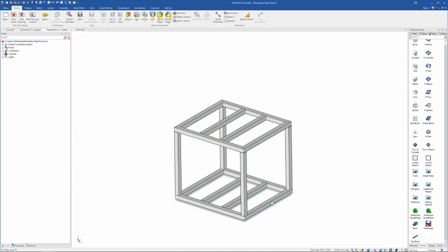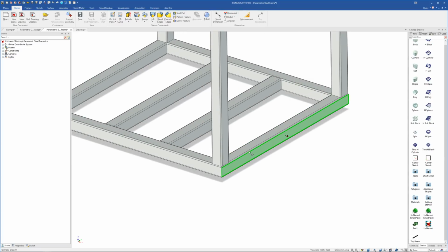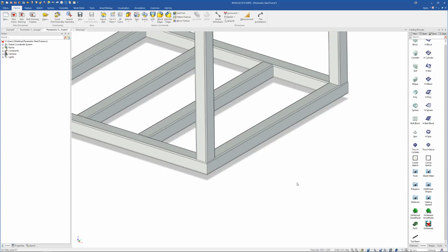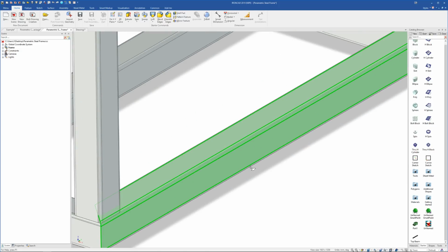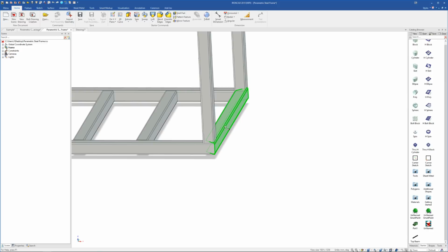Face is a good example, because sometimes you want to select lots of faces, but you don't want to select the edges. And if you're trying to select around with it on any, it can be really easy to select the edges as well. So if we just go here and select down to that level, which is the face level, holding down the shift key here, look, I've accidentally selected an edge, and then I'm getting close there, I've selected another edge. Now I've actually got that edge selected. Whenever you hover over an edge, it's going to select an edge as well. By using the face select or edge select and so on, you can just go around and do it faster, because you don't have to be as careful when you're selecting. It's only going to get faces. So it makes it a little bit easier.